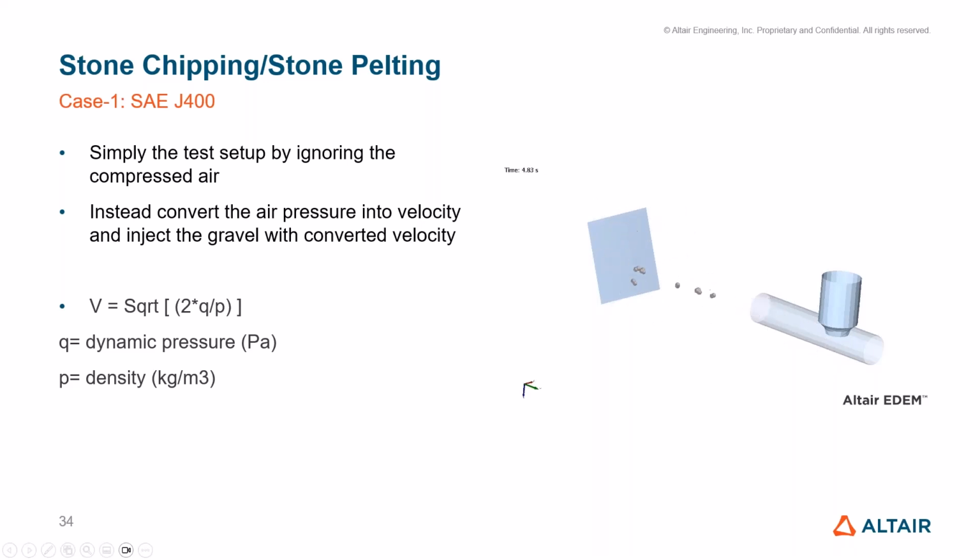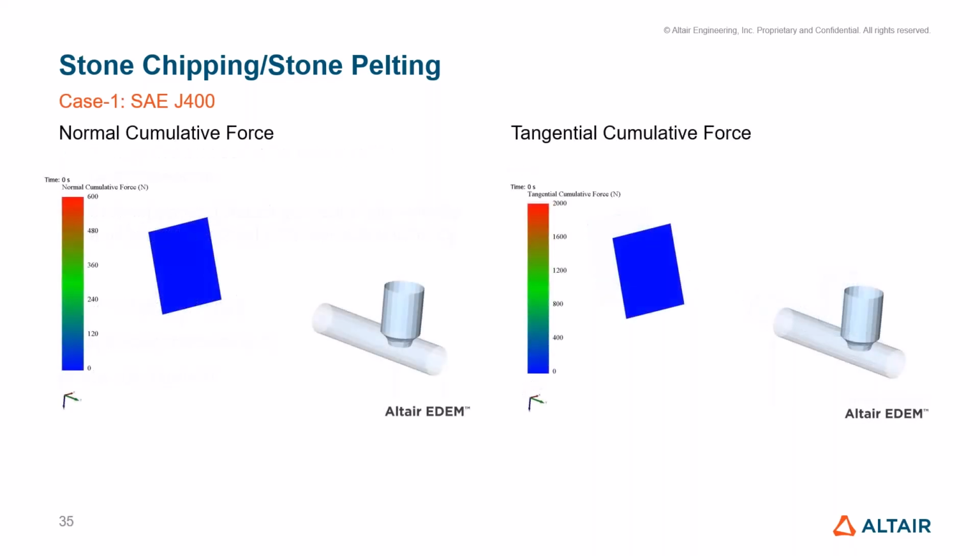We can run an EDEM-alone simulation to understand the injection of the gravel, and due to the gravel impact over the object, what is the force the object is experiencing, and the amount of wear it is subjected to, can be predicted.